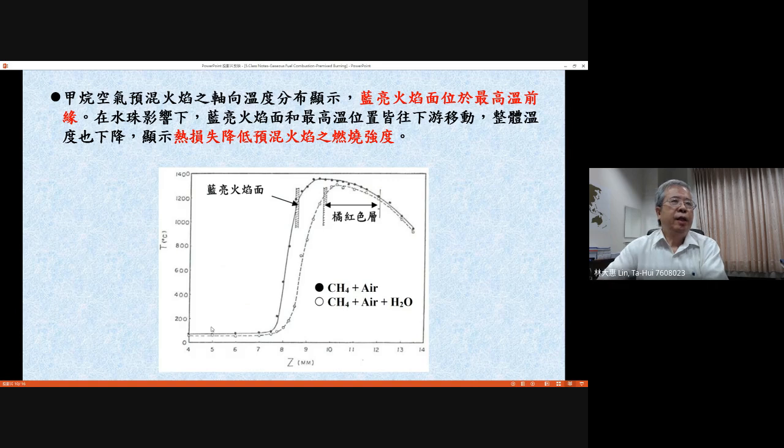Now, let's look at the temperature profile without any seeding particle. Why do we need a seeding particle? Because we want to use the LDV system to do the measurement. Then you need to have some seeding particle. But for the temperature, we simply insert the thermocouple along the axial distance to measure the temperature at different positions of the axial coordinate.